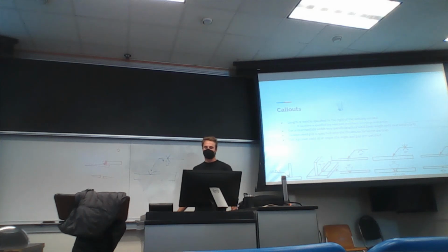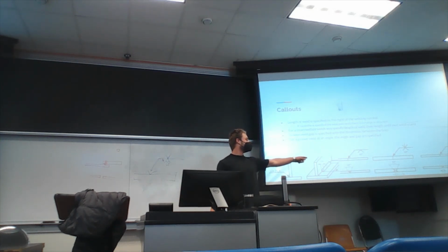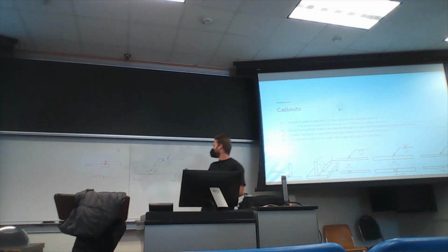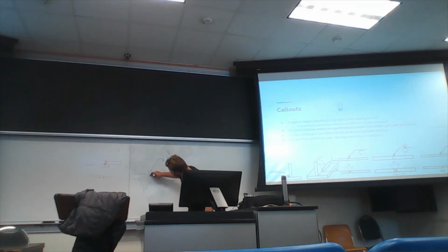And you can call that out differently, so you can see the asymmetric bevel there, where you do 1/8 inch on top, 60 degrees there. Sorry, the 1/8 inch is the gap. So if you put measurement here, now you've got an 1/8 inch of gap between the two plates as you weld them.